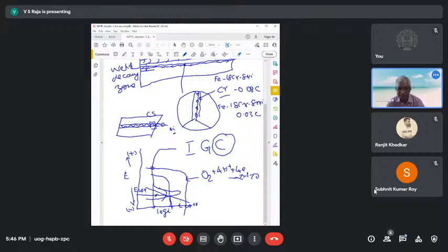It's possible to happen. Now, coming back to the point: you've taken a vessel and you've taken the sulfuric acid, and it is kept here. It is exposed to air, and now it starts passivating. Now you want to close it and deaerate it. You are going to bubble it with nitrogen. There's also an exit, and the oxygen plus nitrogen comes out of this. So over a time period, the oxygen content comes down.